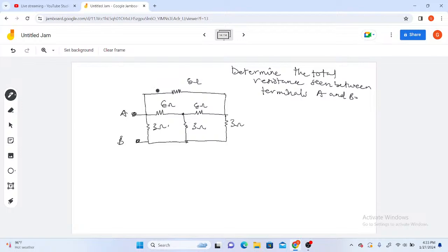And that should bring to mind that we have a delta arrangement here. When I come up here too, you realize that this is 3 ohm and this is 3 ohm. There is a node here. But when I traverse through their path, I'll meet this third resistor, 6 ohm. Here is also a delta arrangement. And if you open your eyes, you can see clearly we have a star arrangement in the middle here.